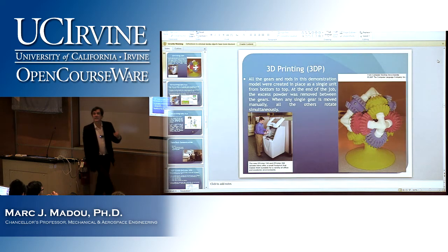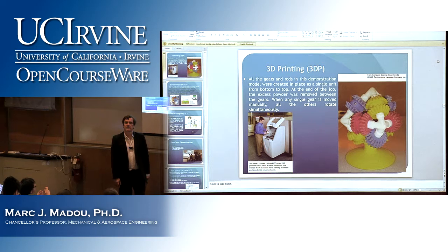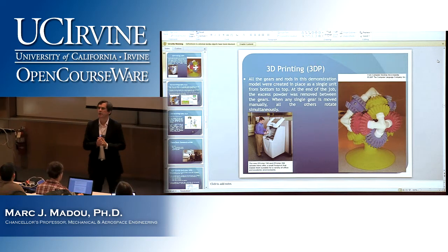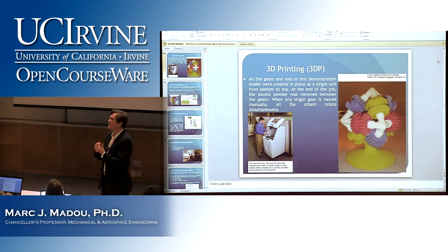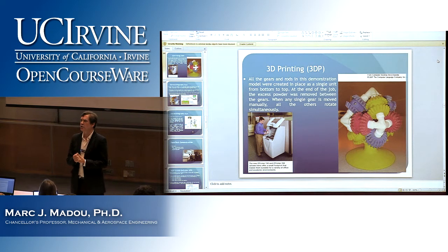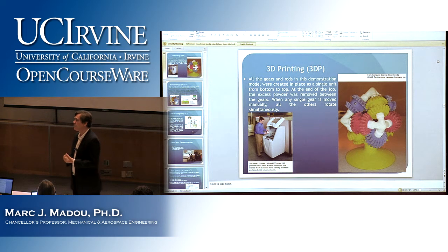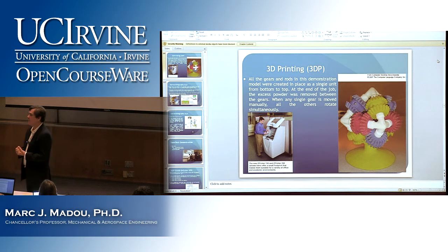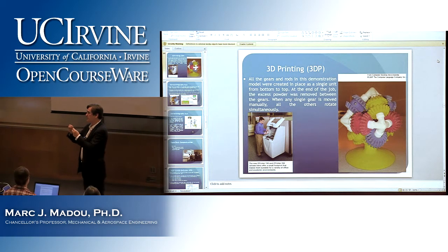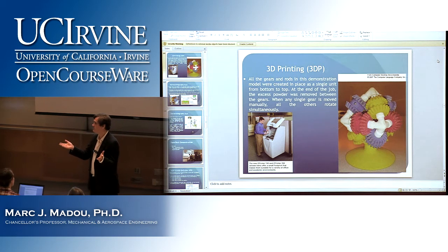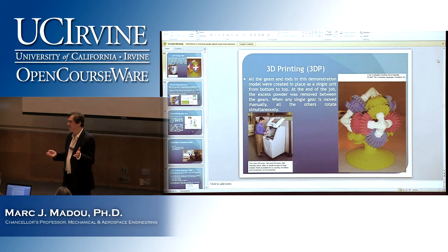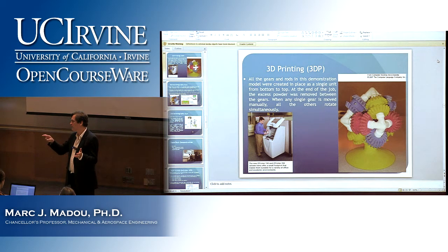Of the different techniques, and I'll compare the three prominent ones, FDM, 3D printing, and stereolithography, which one of these three gives the most functional goods, functional products? No. Now, you remember 3D printing is kind of this powder that you just glue together, so you can imagine it won't have much strength, right? So? Yeah, FDM and stereolithography very close together.